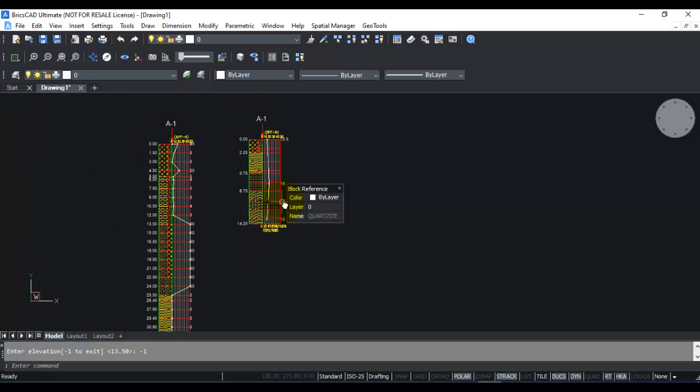So using this method, you can use the geol_strata builder command to create the borehole cross section with SPT values, either in an automatic mode using CSV file or using interactive mode one by one.